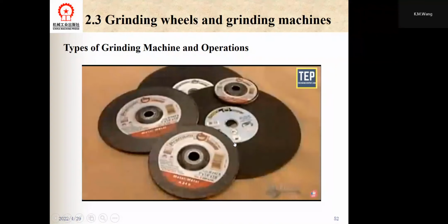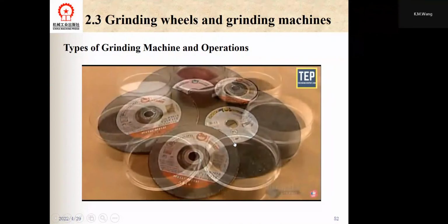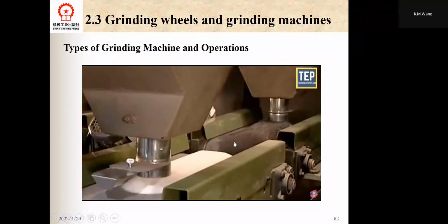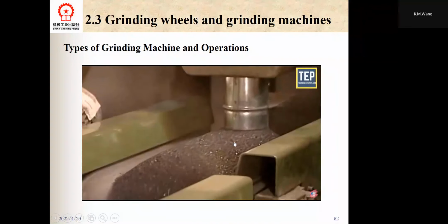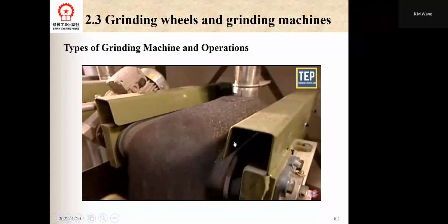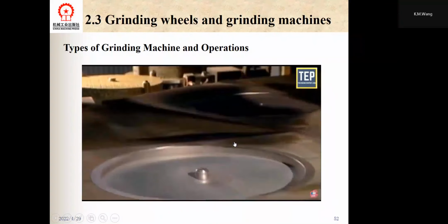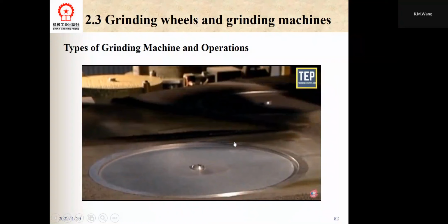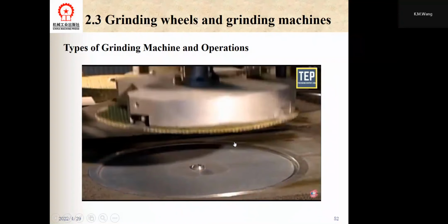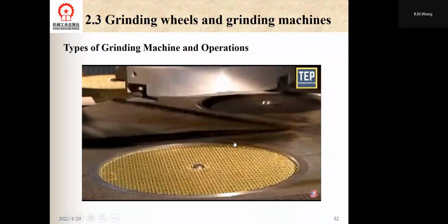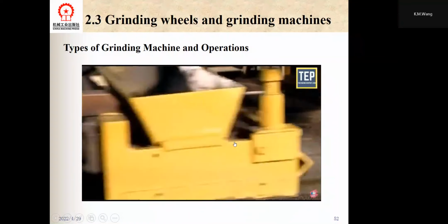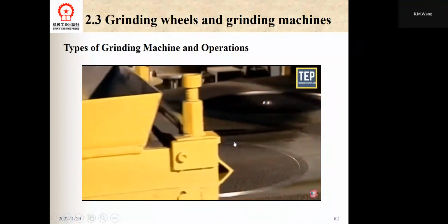A grinding wheel, or bonded abrasive, is made up of thousands of tiny abrasive particles, inserted in a matrix known as bond. A bond refers to the substance of which the matrix of the grinding wheel is made. In bonded abrasives, porosity is essential to provide clearance for the chips being produced and to provide cooling, otherwise chips would interfere with the grinding process.